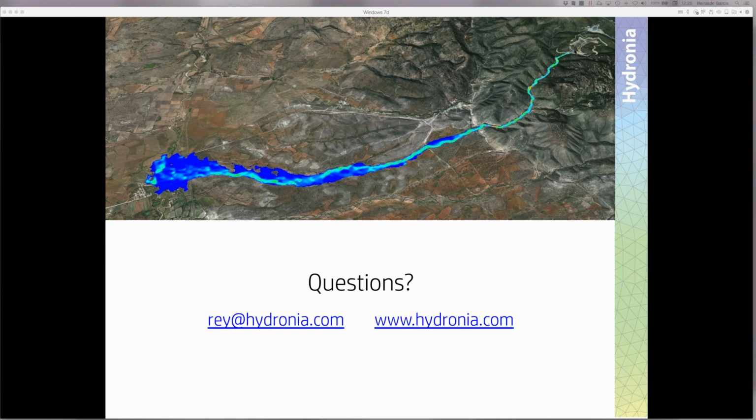Okay, I have a question here. What solution equation method did you use in your HEC-RAS runs? Diffusion wave or full momentum? It's full momentum. We use full momentum in all our runs with HEC-RAS.